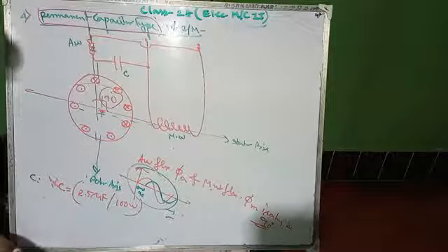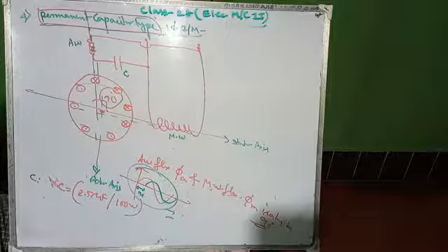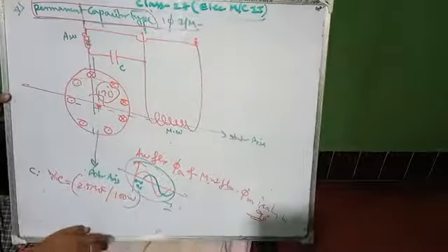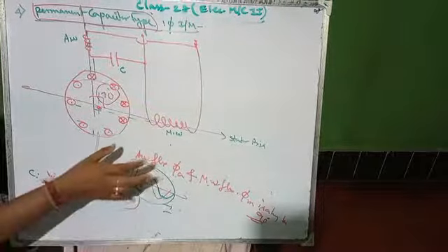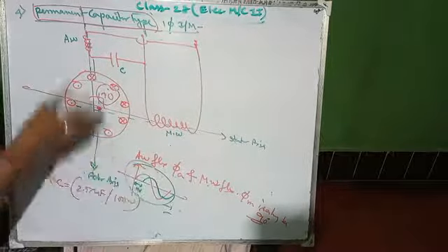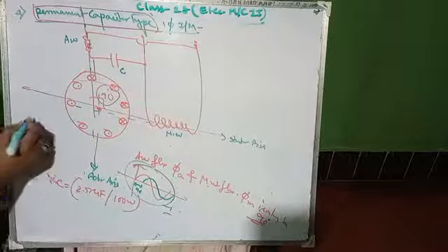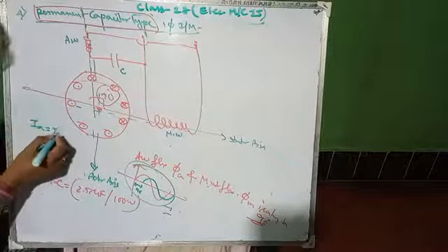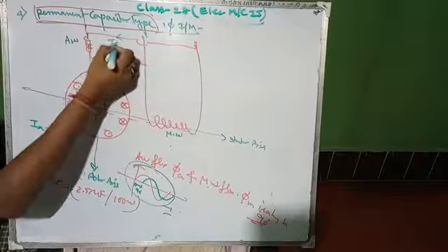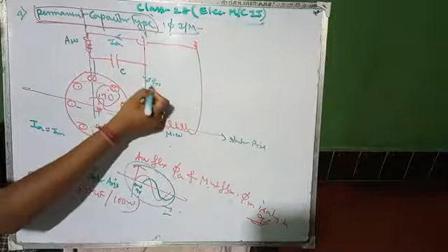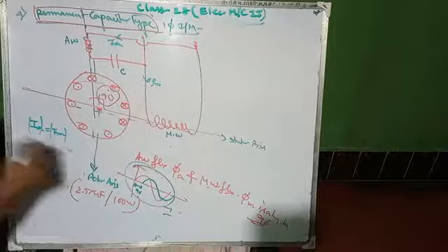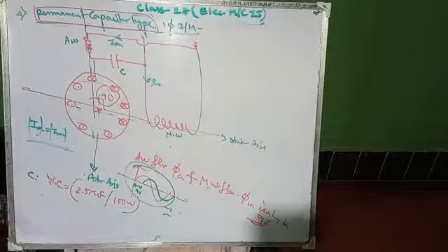Next, IA, phi A and phi M produce the balanced rotating field inside the air gap, and one important concept is that for this case IA equals IM. Whatever current is flowing through one winding and the other, the magnitude remains the same.